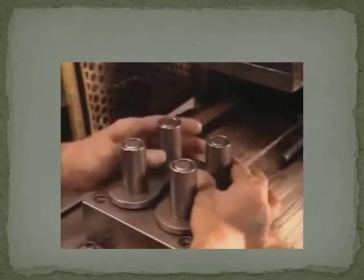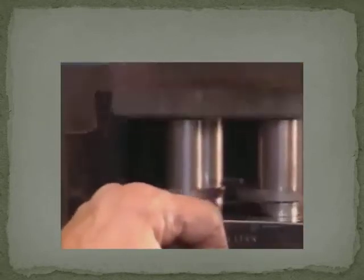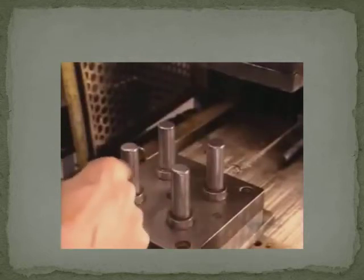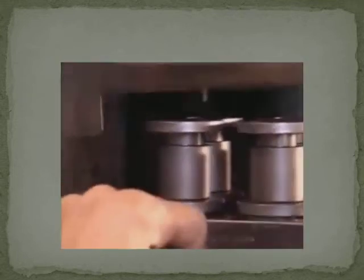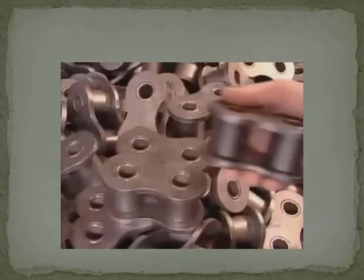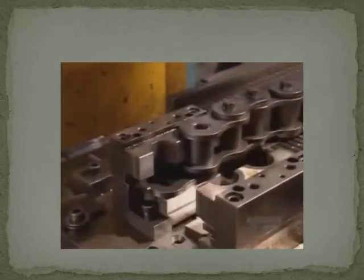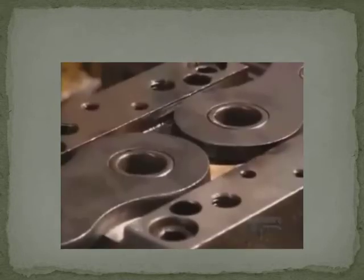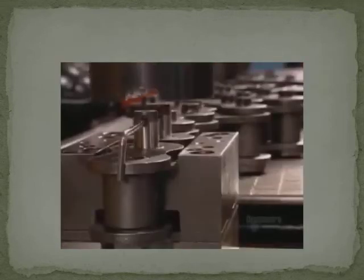Last but not least is the assembly process. The first part is to assemble the inner part of the chain. The part consists of bushing, roller and inner plate. Then assemble between the inner part and outer part of the chain. The outer part consists of bearing pin and outer plate.